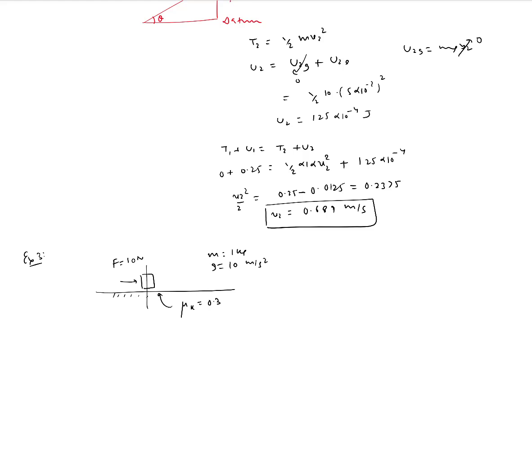And the question is, let's say this is released from rest, initial velocity would be 0, so v1 is 0. Let me change this problem slightly. I'll say that it has acquired a velocity at position 2 equal to, let's say, 5 meters per second. Then how much is the distance traveled by the particle? So if we apply our test, we can see that the test is positive. We are being asked to relate the velocities, or change in velocities, with the position changes. So potentially we can use the work energy approach.